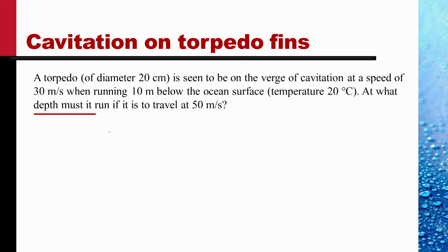Why do we need to specify the temperature? Because cavitation is occurring, and so the vapor pressure is important. And the vapor pressure depends very strongly on the temperature. So we need to know the vapor pressure of water at 20 degrees Celsius.